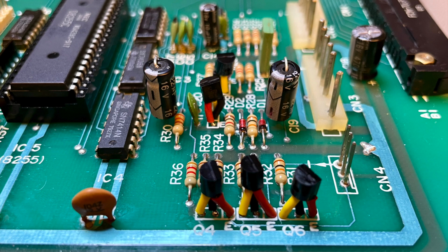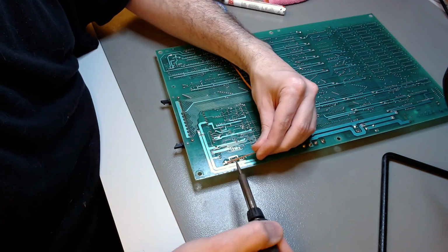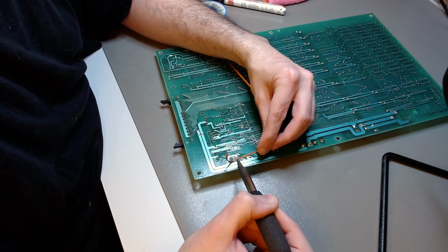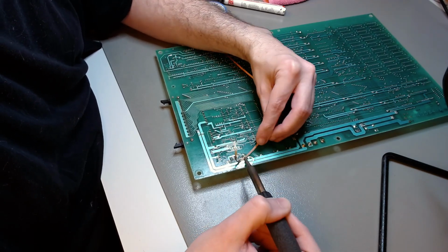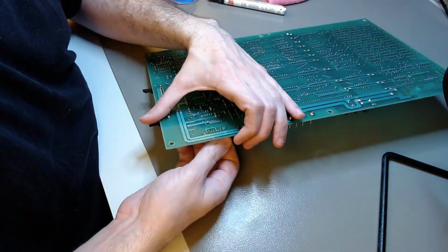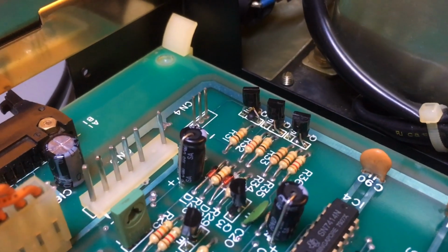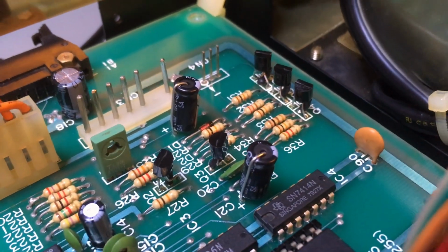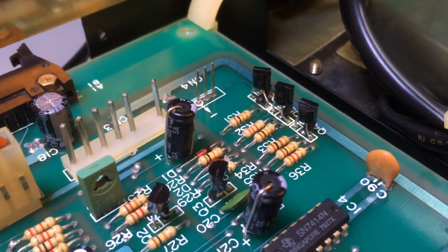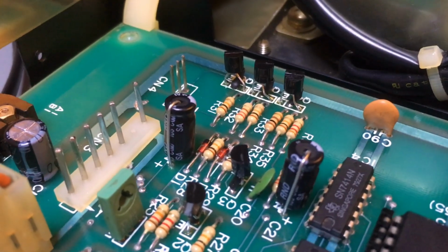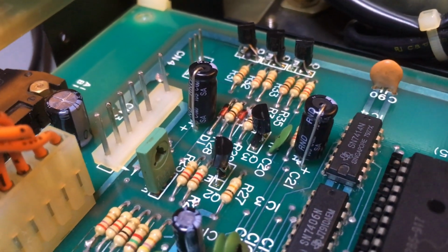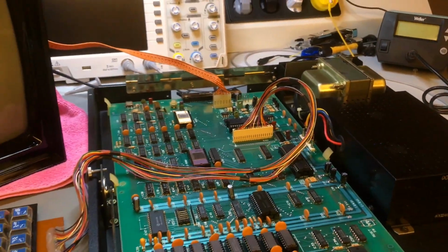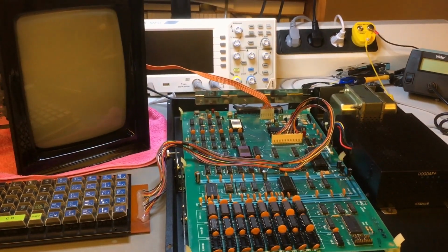But let's continue. And let's swap out these transistors because I already worked that part of the board, or reworked it. I'm doing the gentle approach of desoldering with desoldering wick. It's usually less stressful for the board. So I pulled them out and I installed, again, brand new ones. This time I just put a heat shrink along one pin. It's enough to prevent short circuits. You don't need to exaggerate and put little pieces on all of them like I did before. And hopefully now the base potential will go into the base and the transistor will close and stop the machine from being in that reset.